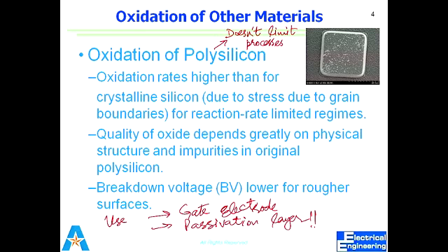I'm not concerned with the quality of the oxide. Even in the case of a sacrificial layer of oxide, I would like to have an oxide layer that is easy to etch away, meaning it should not be that crystalline. So I don't need a better quality because I need to remove it later on. It depends upon our application, what type of oxide layer we need.